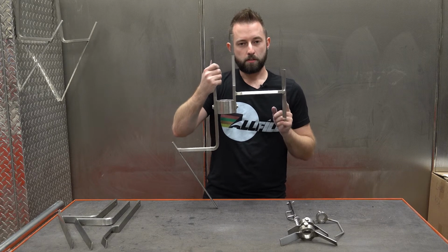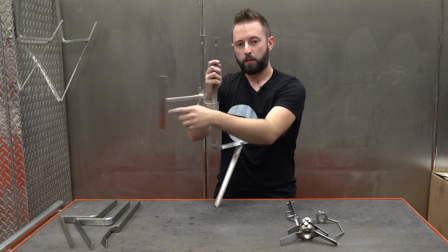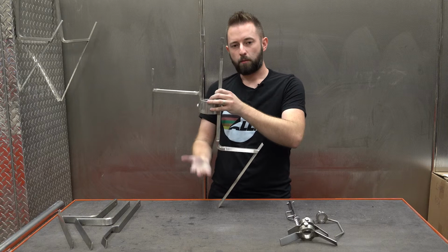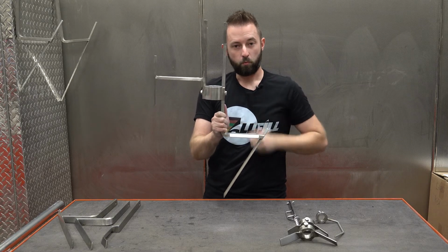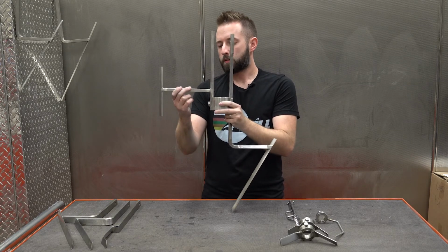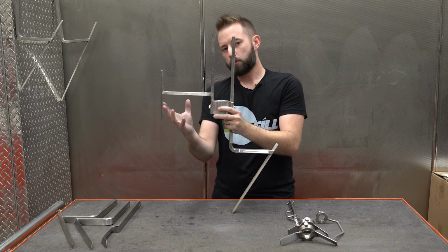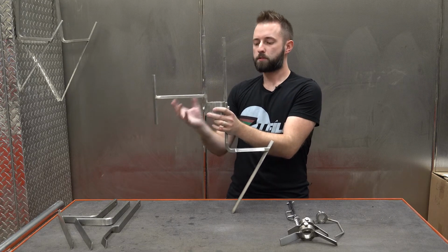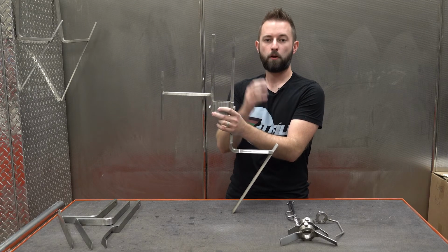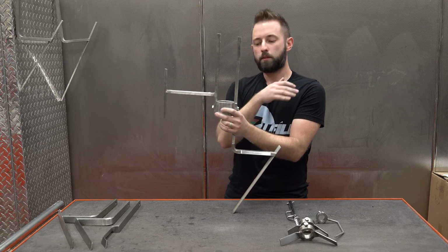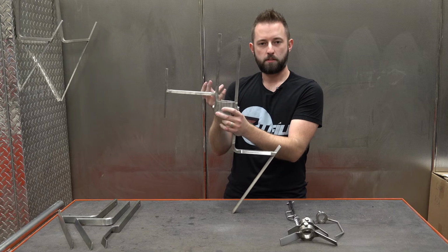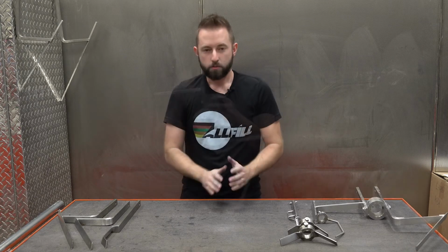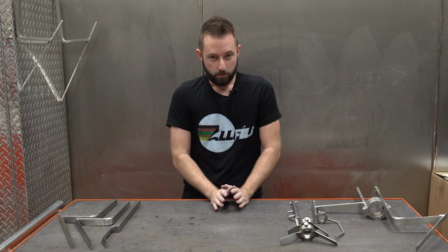What this arm does is it effectively sweeps the top layer without agitating the bottom product, because this agitation blade would not be there. And all it does is it takes that mound that has built up on the infeed side, and it helps to disperse that throughout the hopper, giving the level control the even, uniform layer that it needs to see to shut off the infeed system. So that wraps up our slow speed agitation.